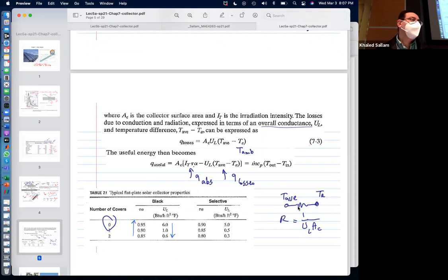between them. And that resistance could be conduction resistance, like a wall, and you have a temperature difference, and you would say, well, Q is delta T divided by, what was it? K area over L, right? So it's L over KA. That was the resistance, L over KA for a wall, right? And for a cylinder, it was ln R2 over R1 divided by 2 pi KL. And for a spherical shell, it was something like 1 over R1 minus 1 over R2 over stuff. But in any case, it's always delta T divided by a resistance.